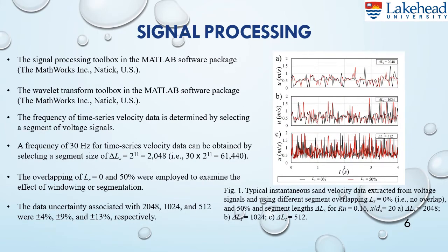In this slide, we will talk about the signal processing. The signal processing toolbox in MATLAB software and the wavelet noise reduction toolbox were employed to do signal processing and to enhance the quality of the voltage signals. To obtain accurate velocity data, the cross-correlation technique was employed based on different segment sizes of voltage signals. As shown in figure number 1,